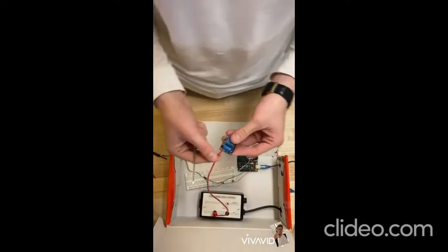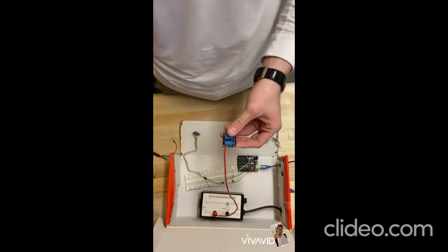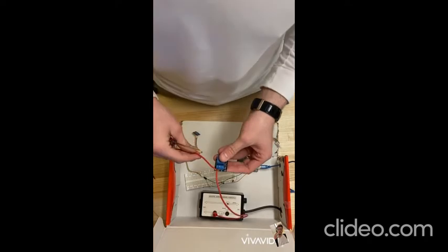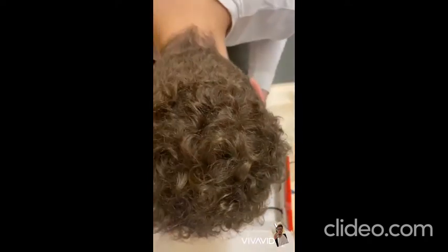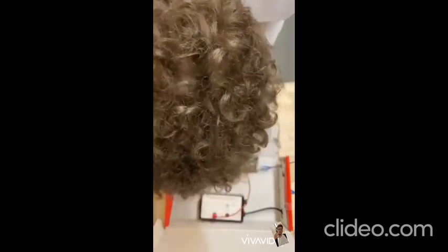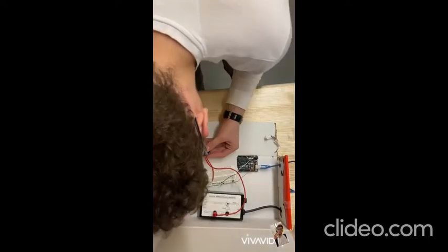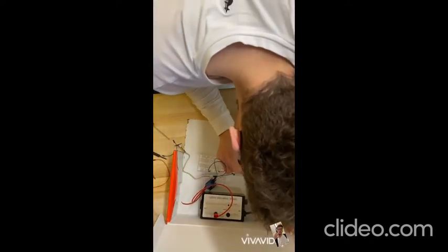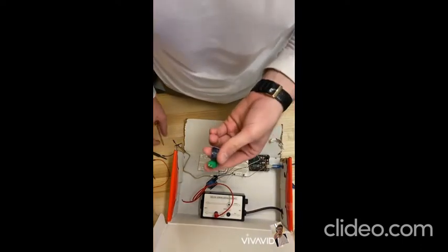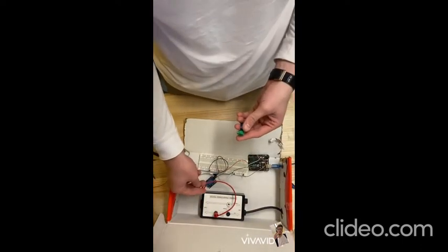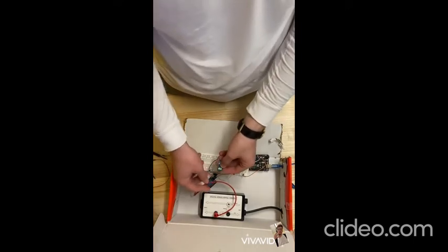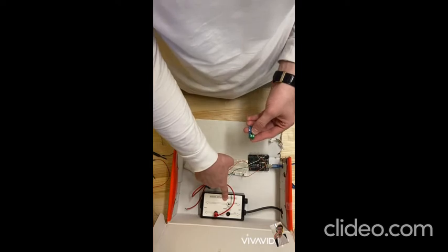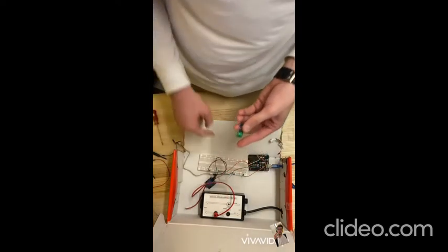And this is the first wire that goes into the relay, and then we're going to get another wire that comes out of the relay and then goes through the current sensor. And then our relay input goes to one of the digital inputs. And then the current flowing through the relay goes through the current sensor and then goes through the transformer tester so that the circuit is complete and the heater can be turned on and off.